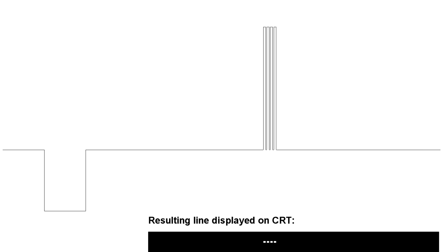Where was I again? Right, okay, so we now have all the steps we need for exploiting NTSC color artifacts. Send a color burst signal for each horizontal line, even though you will not be sending an actual chroma signal for any line, because you're sneaky.